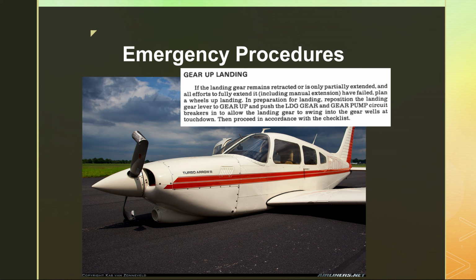Here's what it looks like when a retractable landing gear aircraft lands on the runway without the wheels being down. It does a surprisingly little amount of damage to the belly of the airframe of the airplane. It's going to damage the flaps if they're down. This is a complete engine teardown. It's going to do a sudden stoppage inspection on the crankshaft. I'm pretty sure this propeller is going to need replaced. But to the airframe itself, there's actually not too bad of damage and repair. It could be a whole lot worse. It's going to take some work before it flies, but it could be worse.